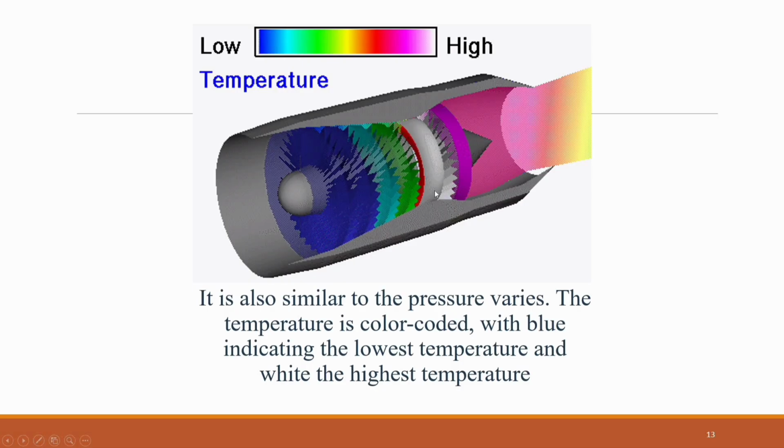The hot, high-energy gases then pass through the turbine. As the turbine extracts energy to drive the compressor via the central shaft, the gas loses some of its thermal energy. Consequently, the temperature decreases across the turbine. However, the airflow leaving the turbine still has a higher temperature than the free stream air outside the engine.